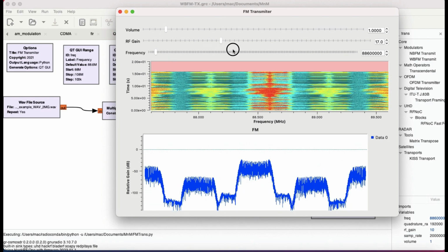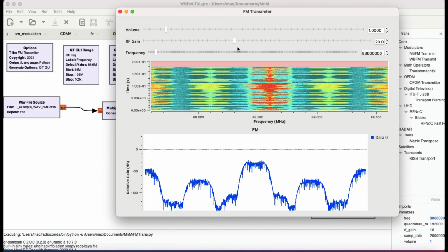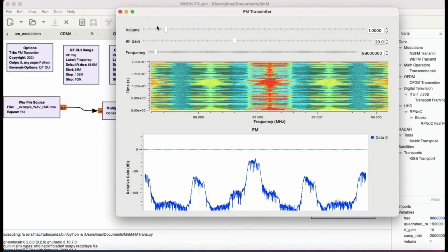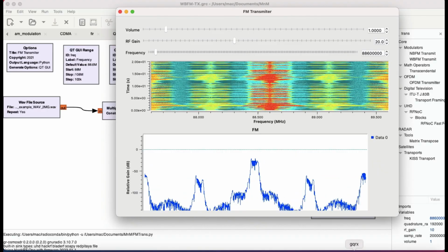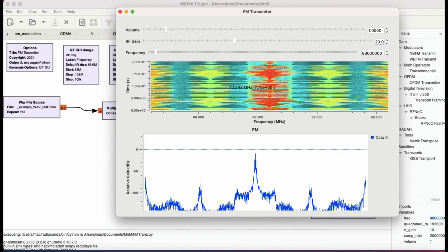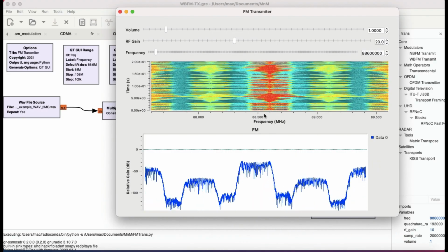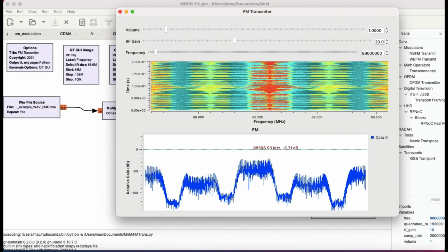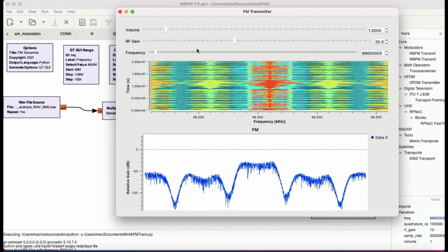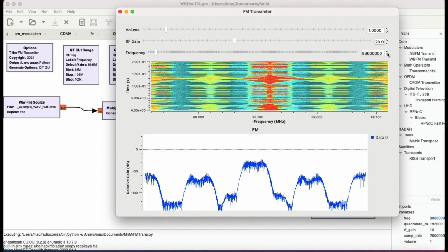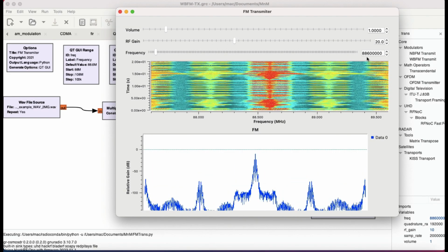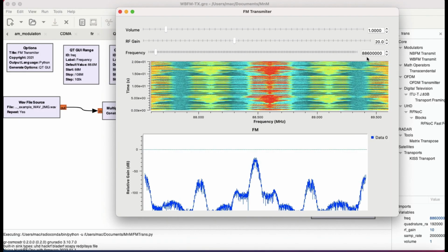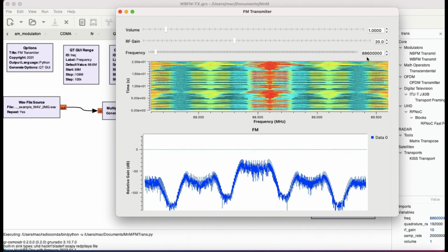This is some RF gain that I can control. So let me change this RF gain to 20. And after everything is set, let's go to my GQRX. This is what the waterfall graph looks like. This is where it's being transmitted, in red. This is what the spectrum looks like. You can change the gain, you can change the frequency as well. We're going to keep this frequency as is because there's no transmission happening at 88.6. So this is being transmitted by HackRF.